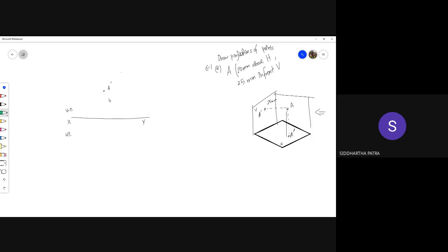Any line that you draw should be a thin line at this point, because you are not actually dealing with lines to represent an edge. Anything that you use to construct or to represent the barrier between two orthogonal planes, all of those lines are thin lines. Only when you start drawing the solid boundary will you have to draw thick lines.